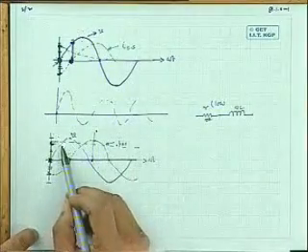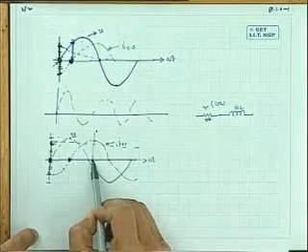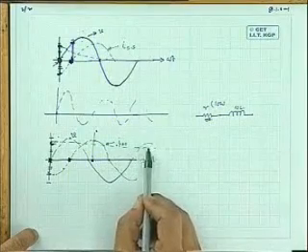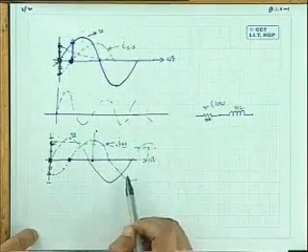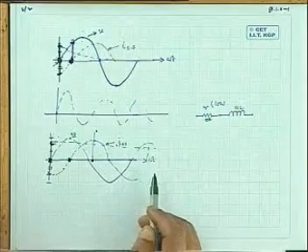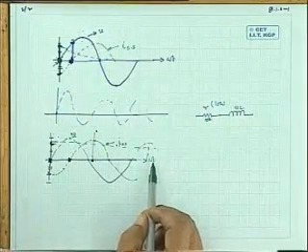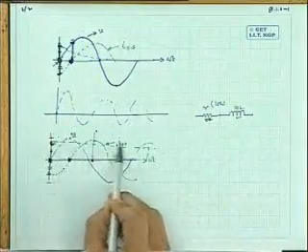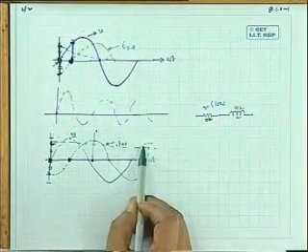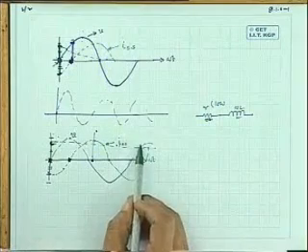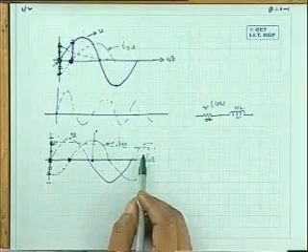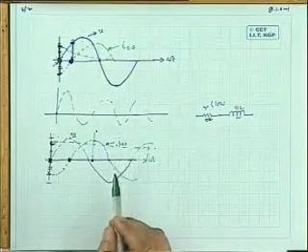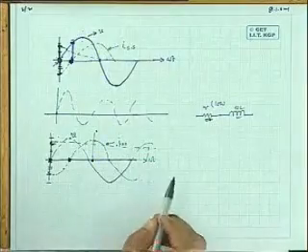Because R being very low, it has not gone to 0 even in the next peak here. In the next cycle, this may persist also, if not twice, but substantially large current will be existing in the circuit. So what I mean to say, there are some situations, and particularly with circuits, where current magnitude may be practically double, and this is called doubling effect, which is relevant in power system analysis for deciding the rating of the circuit breaker, etc.